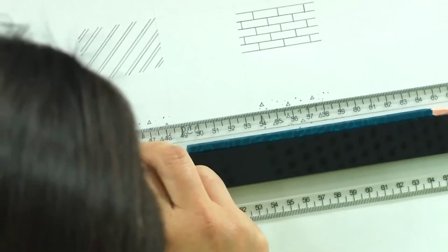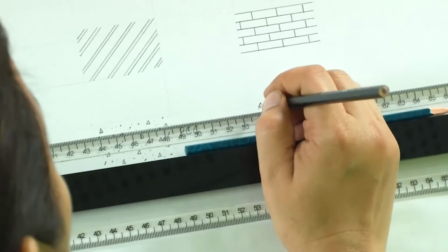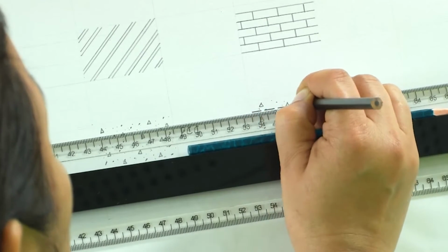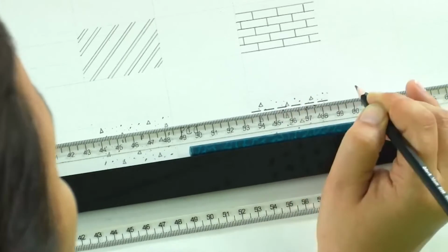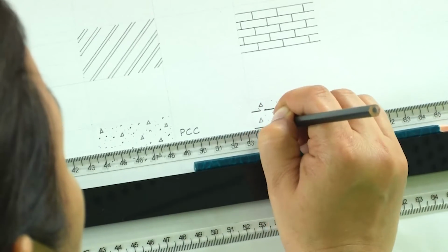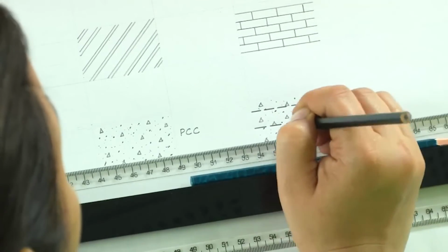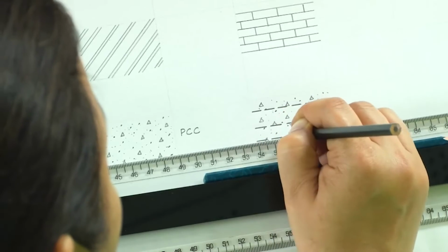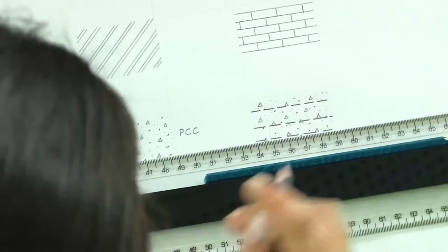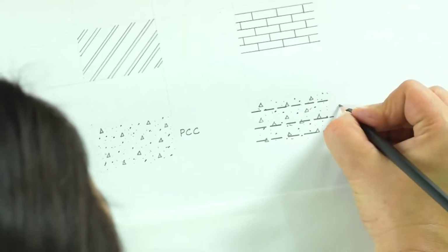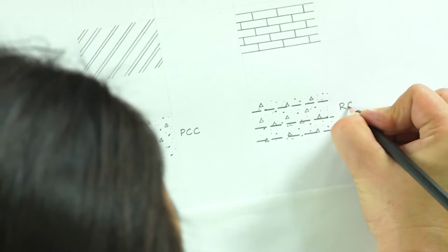And then we will add the representation for the reinforcement. Now, what is reinforcement? It is these steel bars. They will usually not be seen, so we use the nomenclature of a hidden line while drawing the RCC. We will have these dash lines, the hidden line representing the possible reinforcement which might be passing through it. So, this is the representation for RCC.